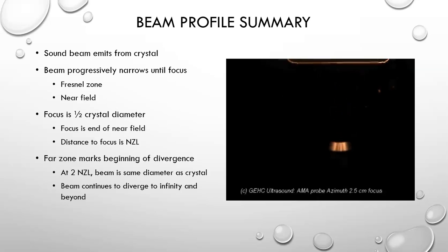The focus marks the beginning of the divergence, and at twice the near zone length, the beam is the same diameter as the crystal again. So the beam continues to diverge to infinity and beyond.